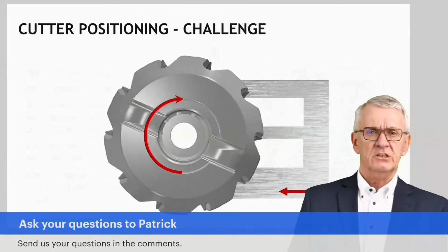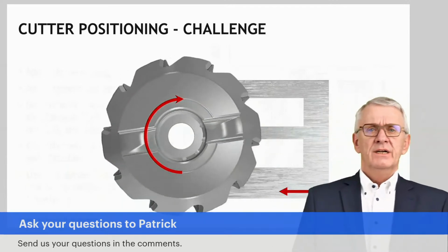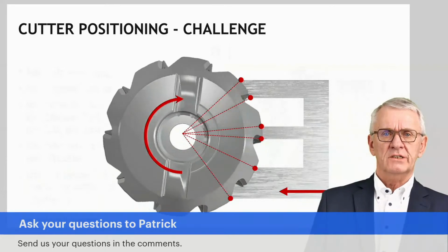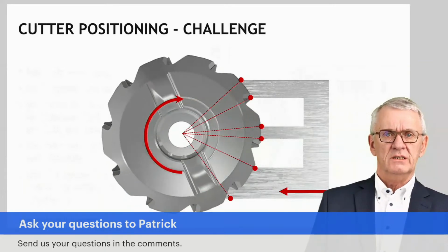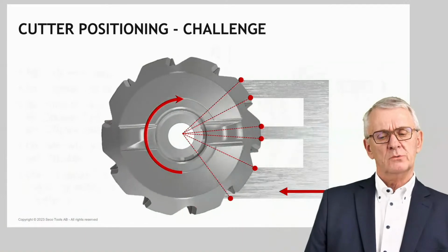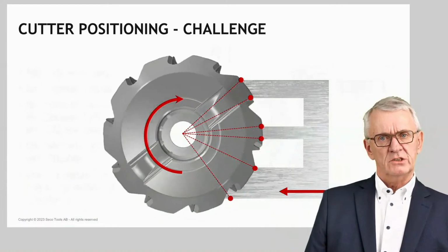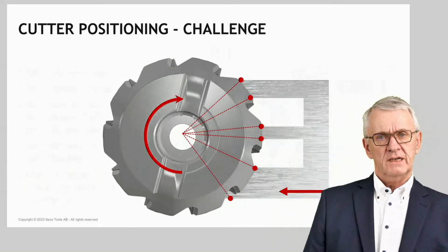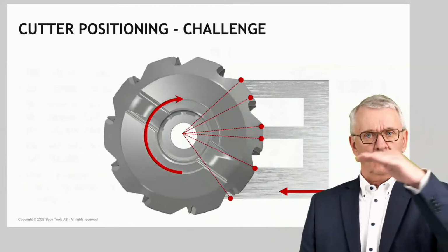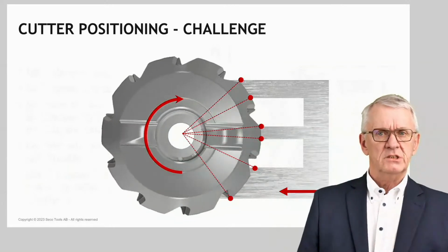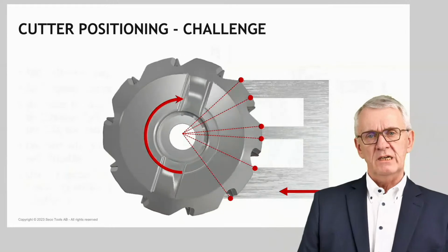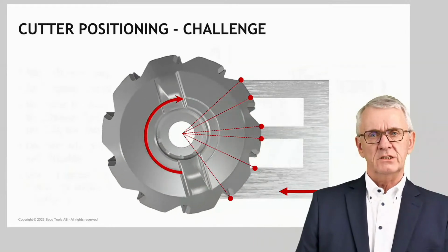Now, of course, there are challenges for you. There's so-called interrupted cutting, a situation I try to simulate here. You have a milling cutter. Think of motor blocks of combustion engines, where very often they do a face milling over the motor block, over the cylinder holes, and then you have a situation where a milling cutter can be simultaneously in 2 or 3 different situations.